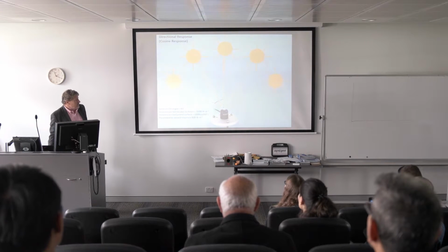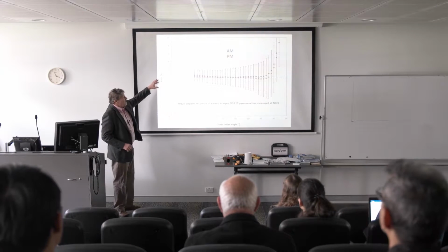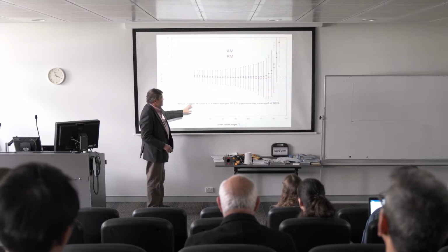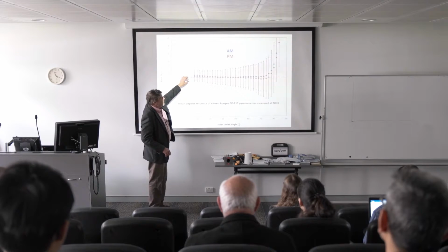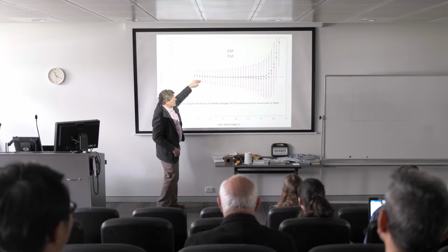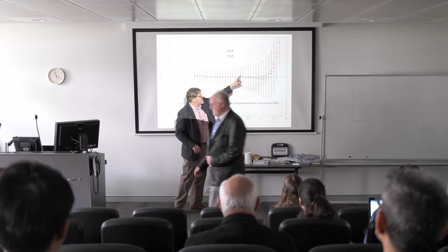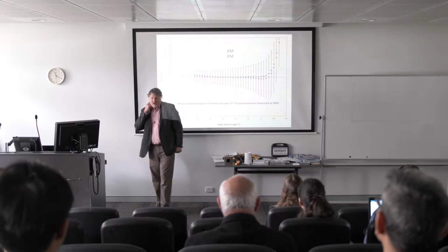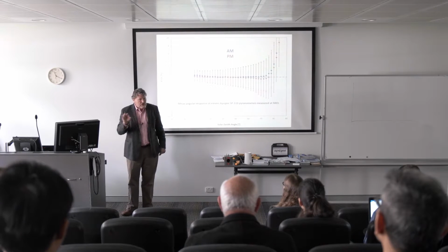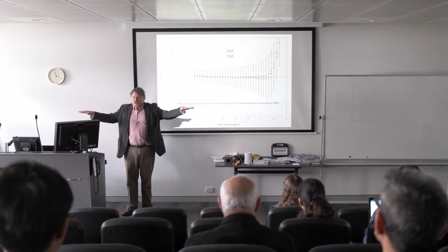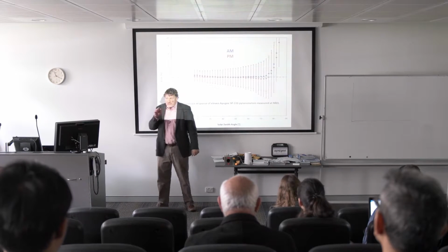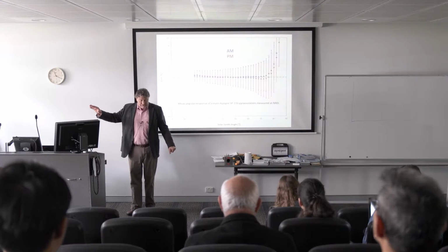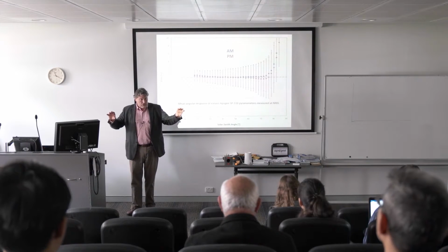So here's all the angles coming into this thing. This is a graph of the angle and the error. In this case, this is a bunch of pyranometers and the standard deviations. The morning and evening are slightly different, so they're really close until we get out to 75 degrees, and then the errors get bigger. This means they're not as accurate at dawn and dusk for those measurements, but there's not very much radiation out here either. It's low light, so a 5% error in low light is not that big of an error in absolute terms.